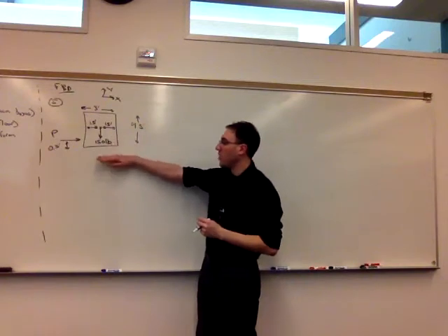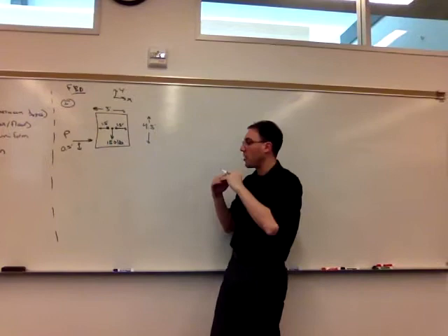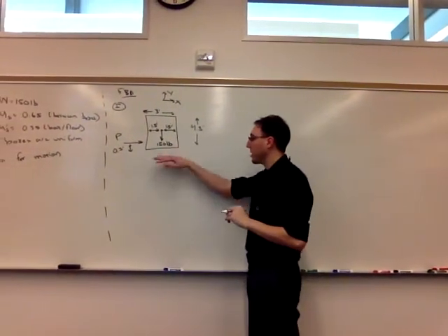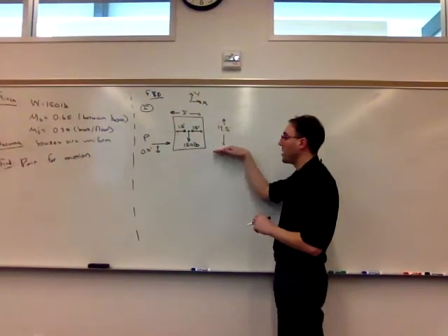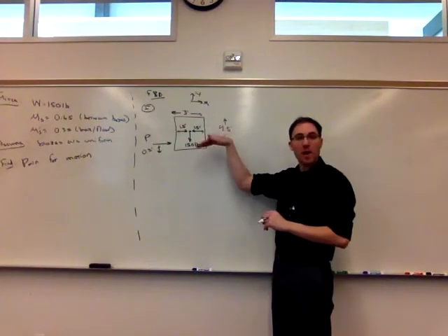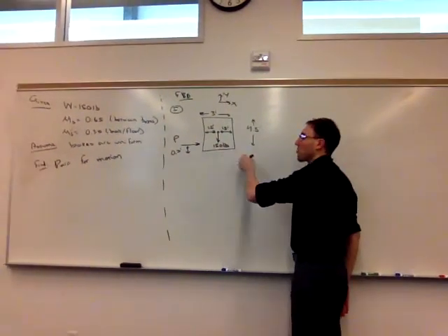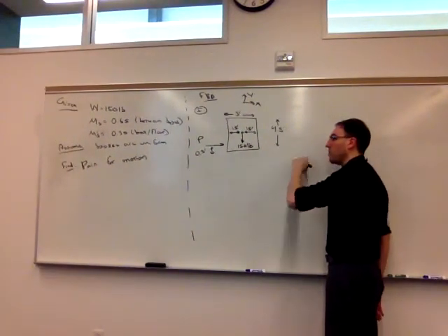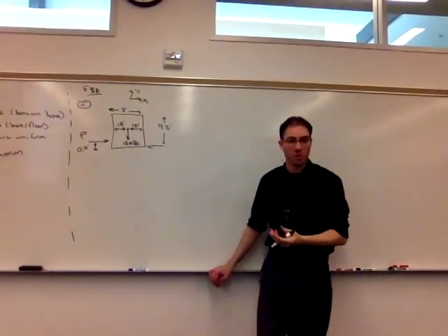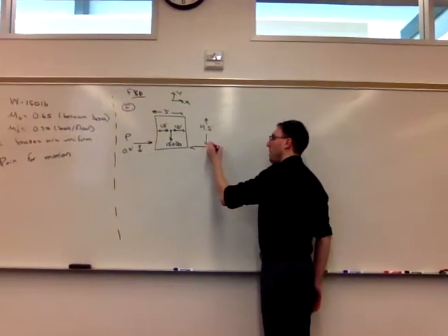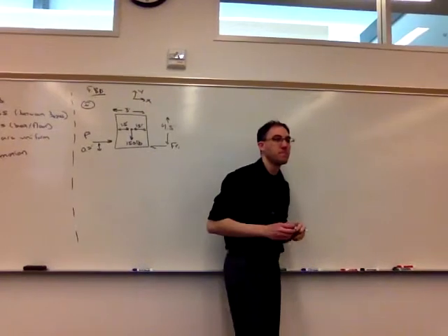Right, so this box, we removed the box below it, but we have to model what those two surfaces were doing. So one thing is there's a friction force between the surfaces. So we know that it acts on this axis. It will act parallel to the surfaces. And we presume that if we push to the right, that the box will want to move to the right. So because the friction force always opposes impending motion, there'll be a friction force I'll call FR1 pointing to the left on that bottom surface.